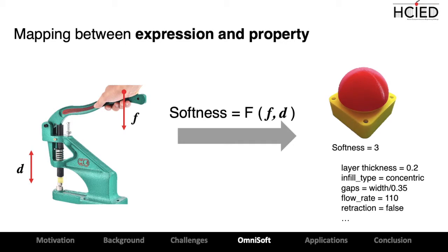We collected lots of everyday examples, and using the commercial device, we measured the softness and provided this as the softness examples. By the softness standard number, we tried many 3D printings by differentiating different printing parameters, and then saw how we can achieve that exact softness by varying these 3D printing parameters. So in the inverse function, we can predict the best print parameter settings to realize the input softness.